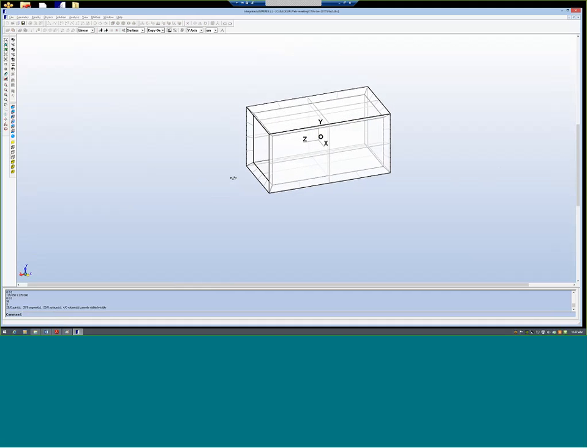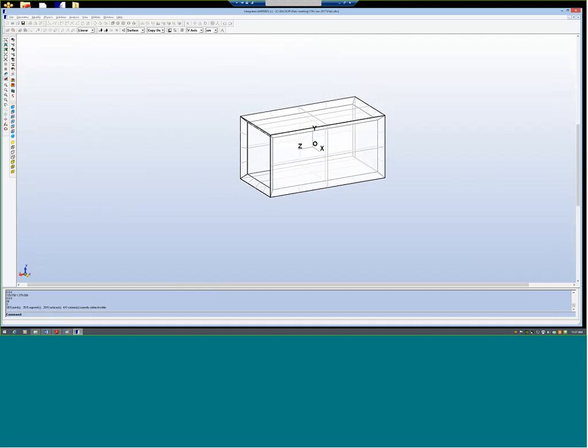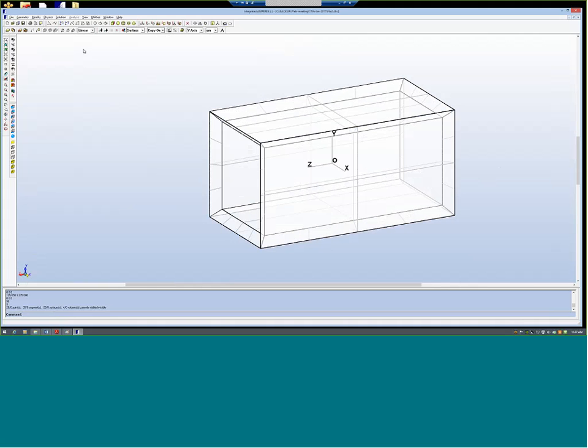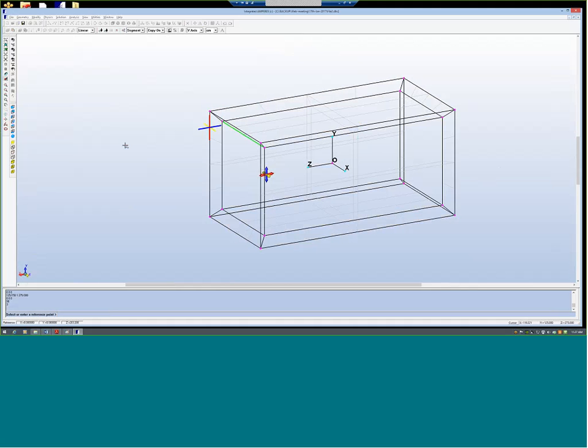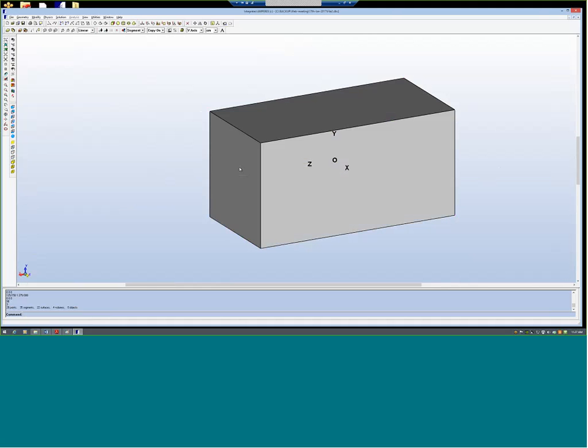So now we have to make the front wall and the back wall. I will create a linear sweep. So take this surface, from here to here. Similarly, this one also sweep downwards to close this. Now you got the required surfaces to define the volume, the front wall. I will define the front. Now I define the volume here.